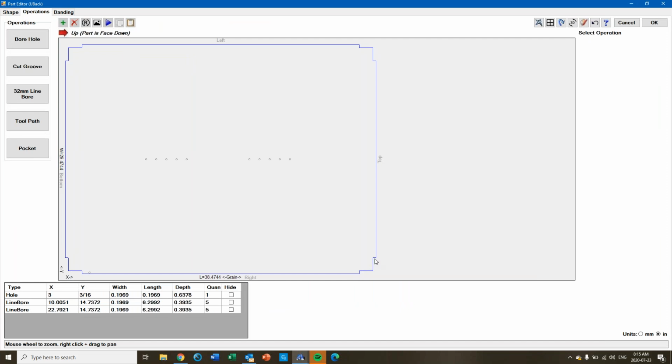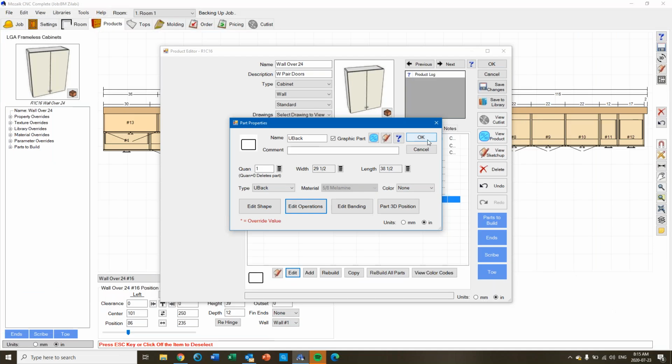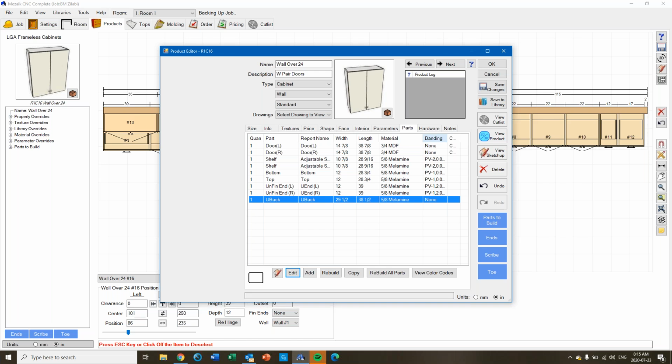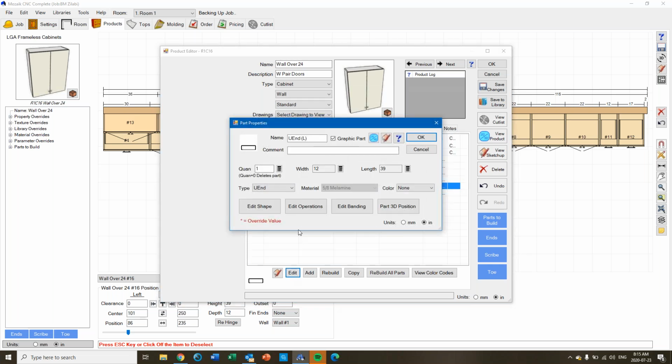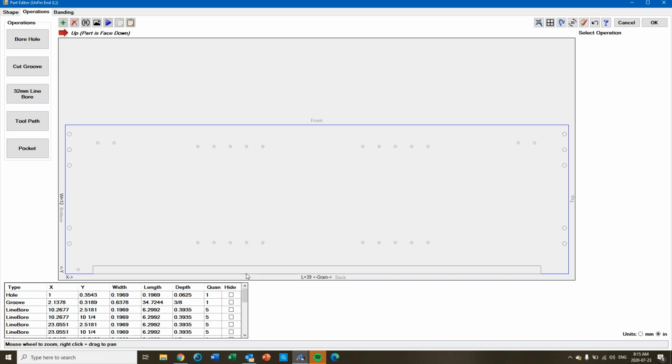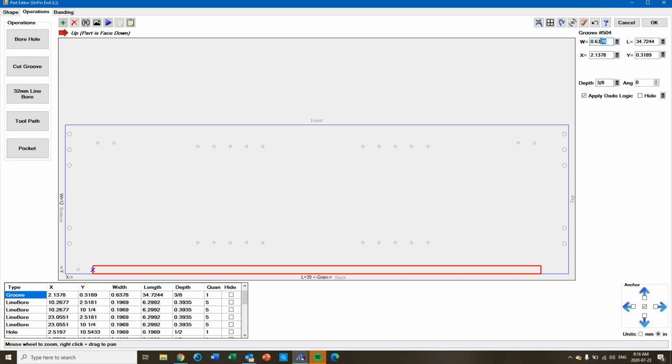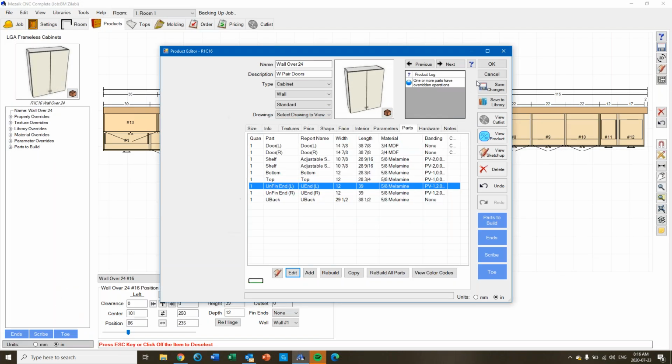Yeah. So now you've made everything a lot easier, but you were just getting really lucky that you weren't clicking flip parts, because you were going to get burned someday. If you weren't clicking flip parts, the width of this data right here should be 0.6378, okay? But yours, before this, was actually only being machined 0.625. And that's not right. It needs to change with the material thickness. That's why it was leaving a little bit.